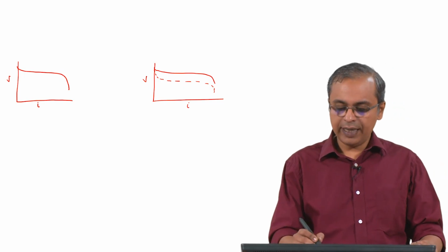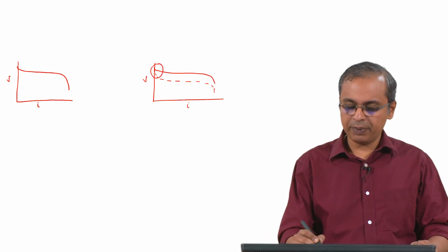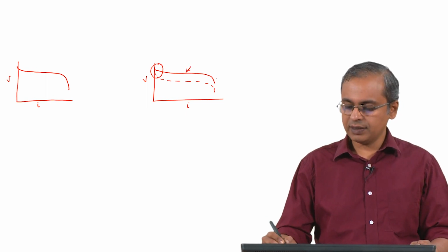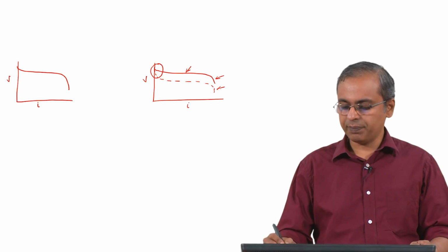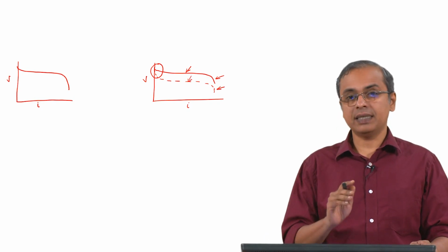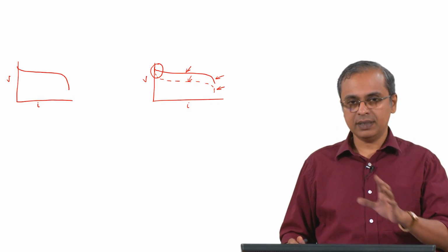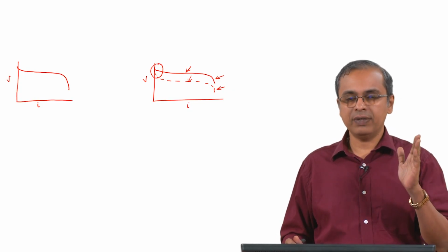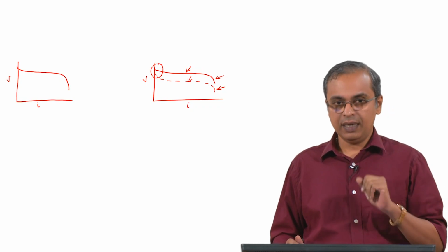This means the activation energy losses alone have gone up in a very dramatic manner. On the other hand, the ohmic losses as well as the concentration losses are roughly the same. So, it means that they are not affected, and this is a very nice way in which you are able to isolate the region where the deterioration is occurring in the cell.